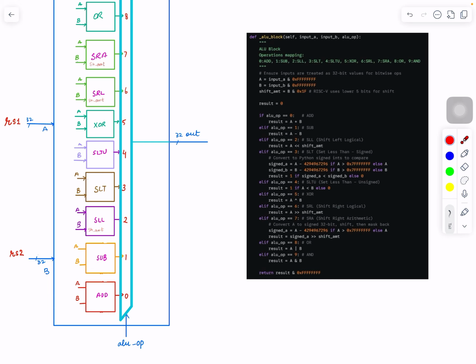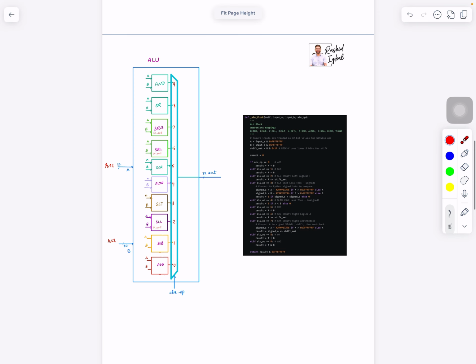So the value decides which input into the mux is propagated eventually to the output here. And eventually this ALU has two 32-bit inputs and one 32-bit output. You understand that? So this is a very combinational-heavy circuit. If you look at our microarchitecture so far, there is a lot of logic, especially if you have add. Later, when we go into implementation, we will look at how many logic levels there are, and that will be our critical path through the ALU.